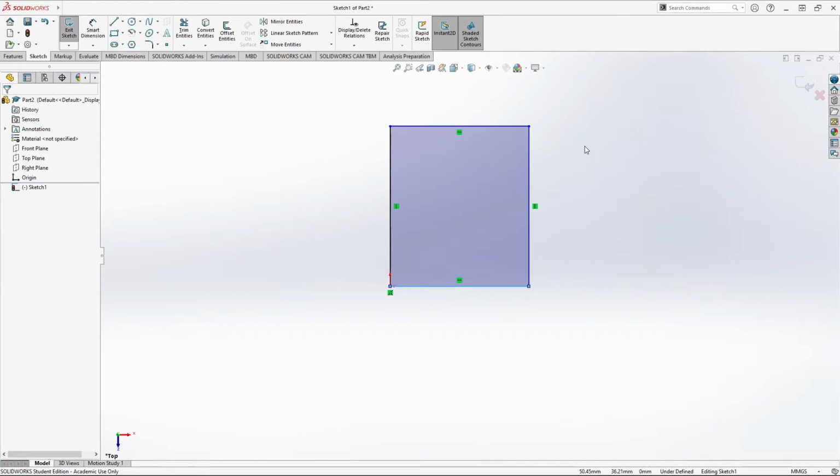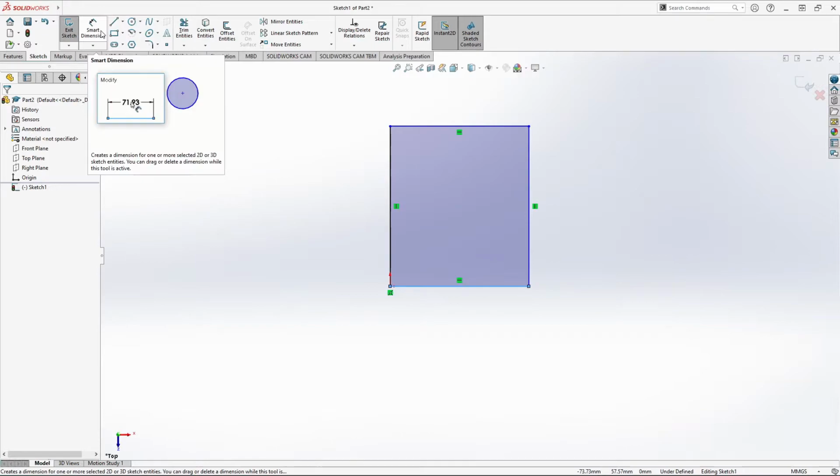You create a sketch. You don't need to make the sketch precise when you're actually drawing the sketch, but once you've created that sketch, you then go in and you start defining dimensions and various constraints that link the lines making up that sketch. So we're just going to define some dimensions, and don't forget this is a square, so all sides are going to be equal. So as long as we define the same length for every side, we should be fine.